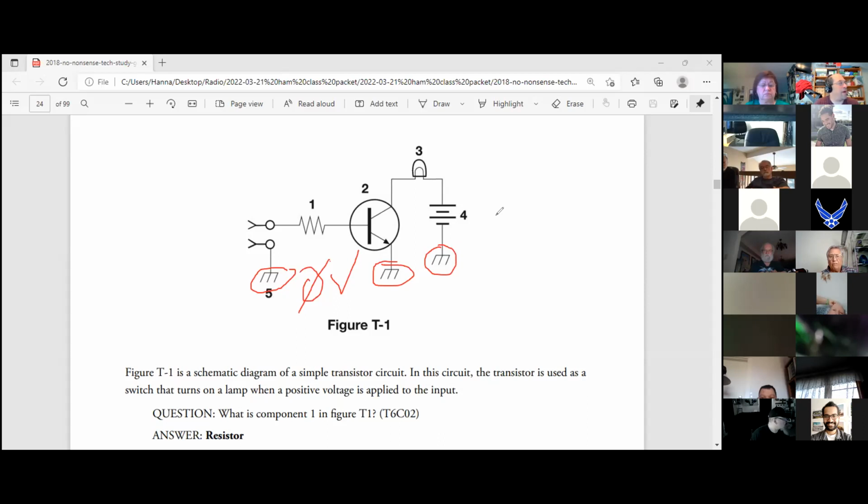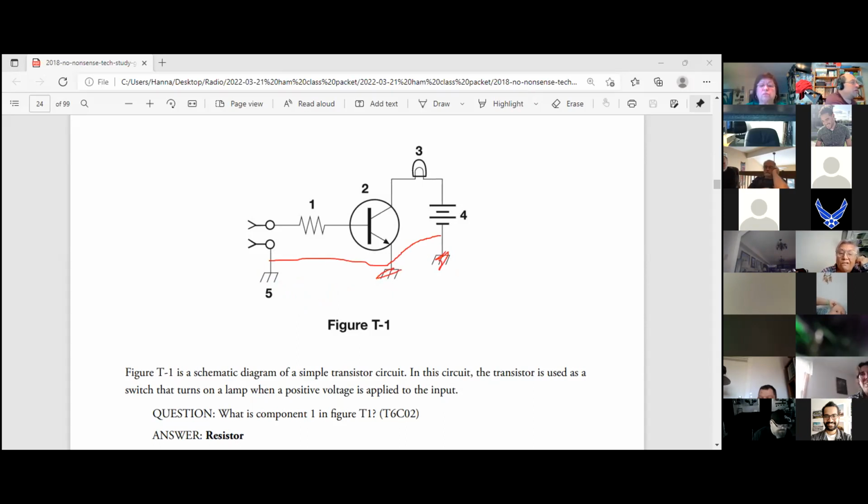Well, how do I know that those are actually all the same point? Same symbol. That's the same symbol, and they're all connected to the earth. And it's assumed that the earth is a perfectly conductive thing. So our 0 volts is connected everywhere. So really, if I wanted to, I could draw it like this, and I could get rid of the ground symbols. I could connect all my grounds to one point if I really wanted to draw it that way, because they're really all the same.